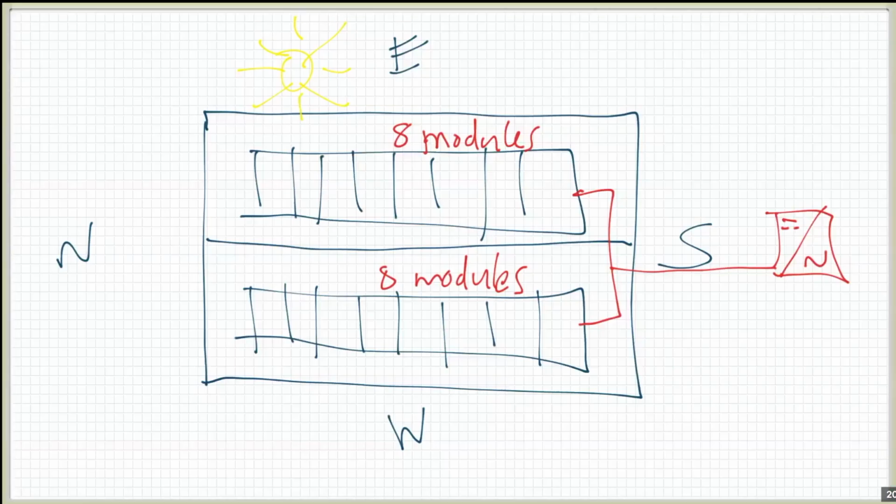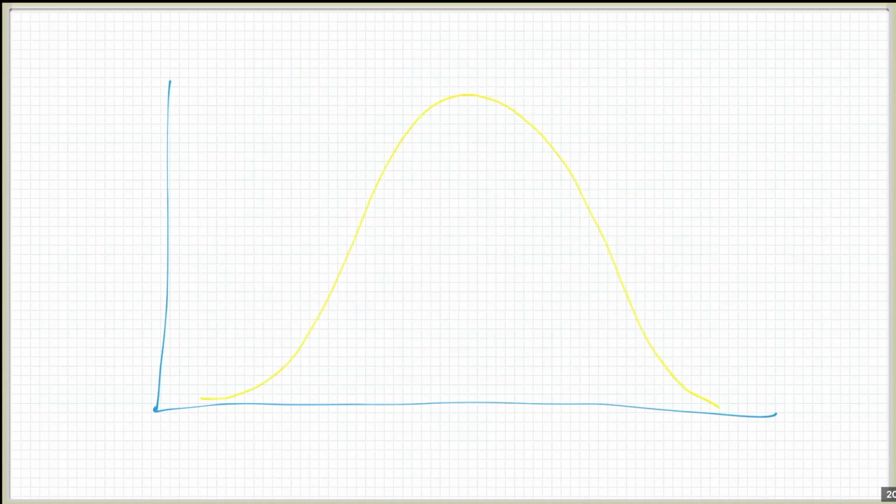There's a common misconception that you'll blow up an inverter if you ever have a PV array that produces more power than the inverter can output. And that's basically wrong. It's assuming that the inverter has no control over the array, but the reality is the inverter does. The inverter is a smart load. Now let's draw an ideal curve on a sunny day. So there's an ideal curve. So this is power here.